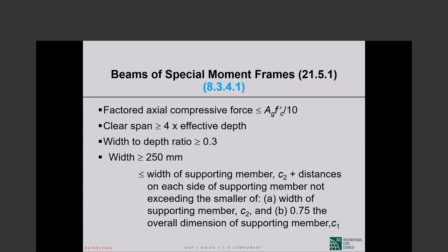I don't understand it. I mean, when we did, if it is a slab subject to gravity loading only, then the gravity loads that will cause bending moments are, there are two load combinations, 1.6D or 1.4 dead plus 1.7 live.